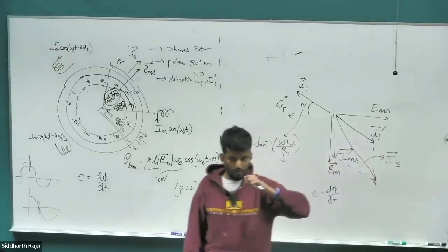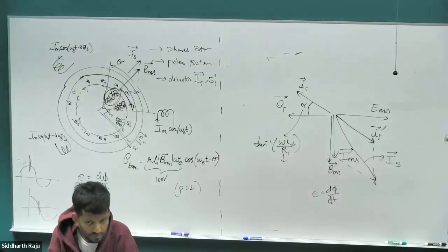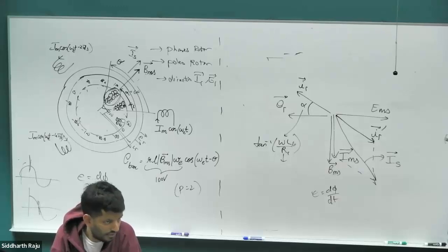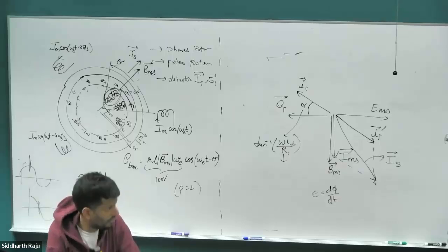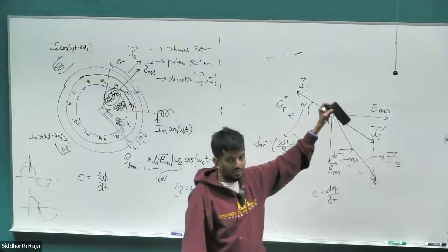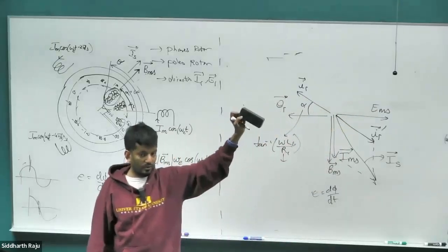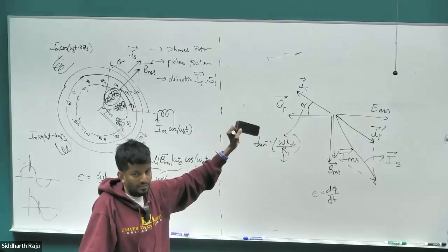How will I figure out the terminal voltage on the primary side, on the stator side? What else do we need? Back EMF from the rotor spinning. That is already attributed. Then there is no rotor magnetic field at all, right? Because whatever the rotor magnetic field was is instantaneously cancelled out by the stator magnetic field.